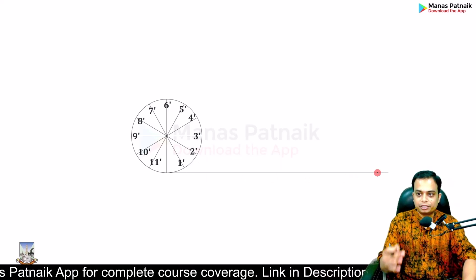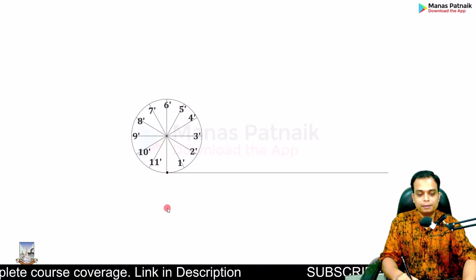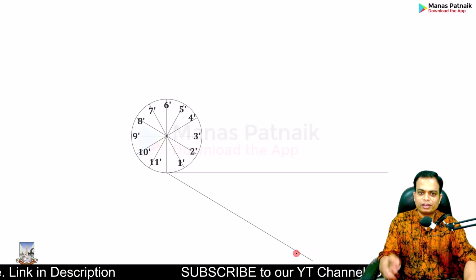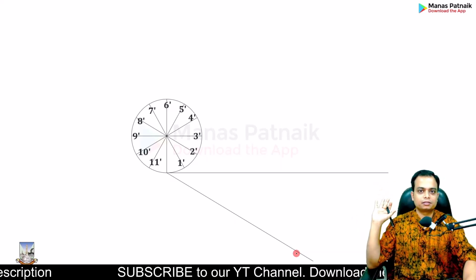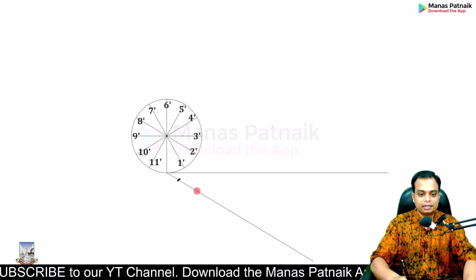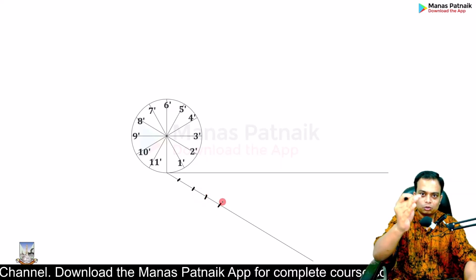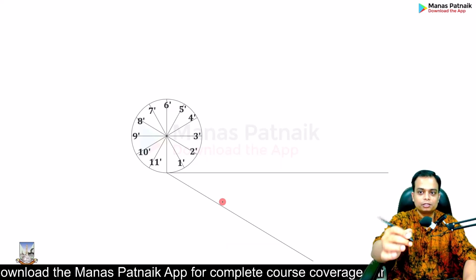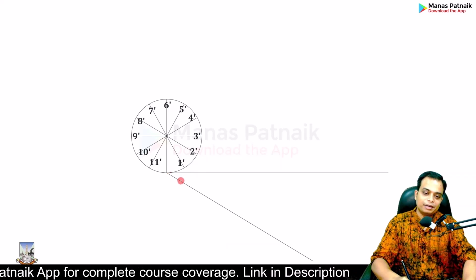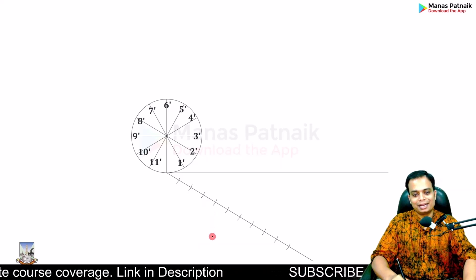This is going to be the line division technique, which we have used quite a lot in engineering drawing. Start point. From here, draw a line randomly of any length, let's say 120, 130, 140 millimeters. Now you can keep your manual scale over here, and at regular intervals of 10 millimeters, keep on marking these points. I am making arcs of 10 mm radii, because if I start making points, it won't be visible to you on the screen. Here we go. 2, 3, 4, 5, 6, 7, 8, 9, 10, 11, 12.